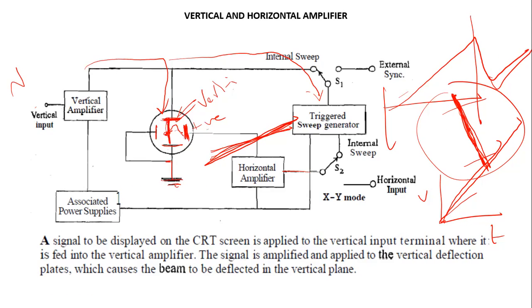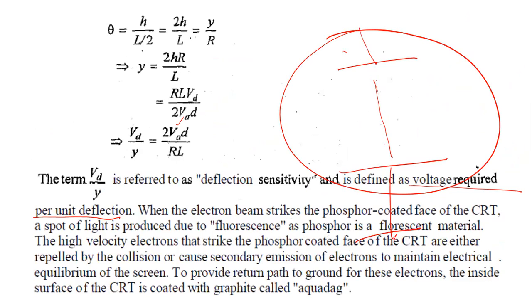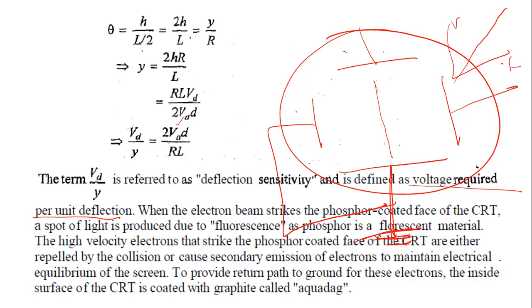So instead of traveling up and down, depending on the signal given to this vertical deflection plate, the other end is grounded. Once you have a sweep signal here, this is also connected to ground. When you supply this kind of linearly increasing voltage here, V versus T, sawtooth, instead of traveling up and down, as it travels up it is also deflected in this direction.